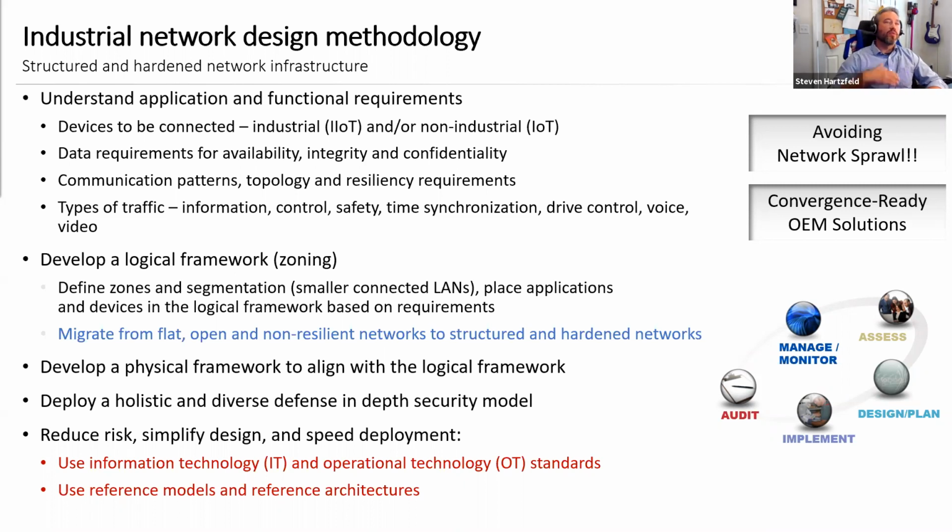And as more and more Ethernet devices are added, more switches are daisy chained, more things are hung off the network, it gets less and less reliable and exponentially more difficult to troubleshoot, to maintain, and to manage. And to avoid this, we want to ensure that any architecture change is done with a specific purpose in mind. And we've taken steps to ensure that the rest of the infrastructure can support it.